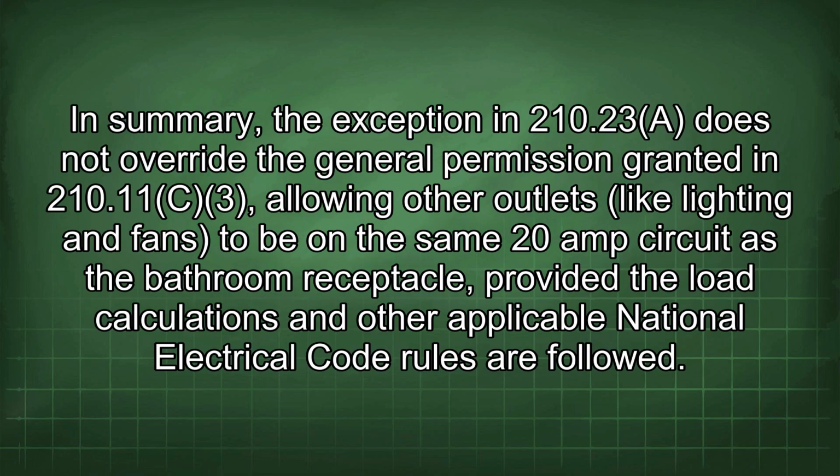In summary, the exception in 210.23(A) does not override the general permission granted in 210.11(C)(3), allowing other outlets like lighting and fans to be in the same 20 amp circuit as the bathroom receptacle, provided the load calculations and other applicable National Electrical Code rules are followed.